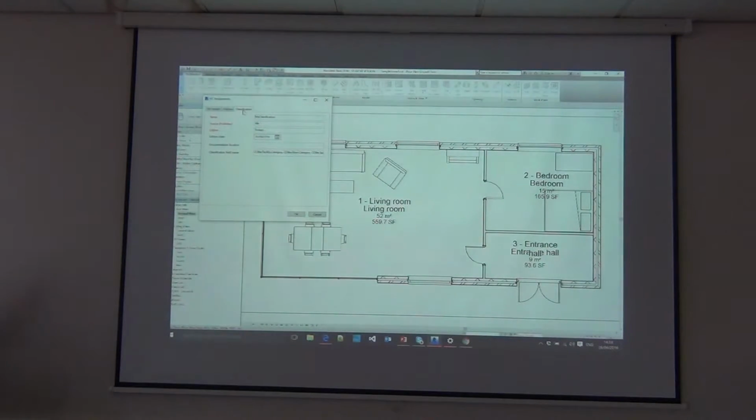So once you've agreed it with the client, this is where you fill it in, and the data you put in here are the actual, if you're using Omniclass or Uniclass or NRM1, you put in the details here so that when this information is exchanged, not just human beings can understand the classification, but computers can. So a computer will then be able to open that IFC file up and go, this is classified in NRM1, these are all the doors, because it knows how to talk NRM1. Okay? Really important to get that right.